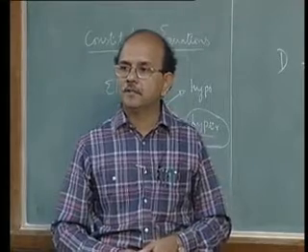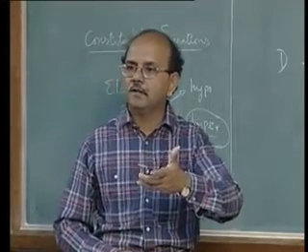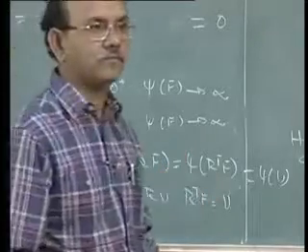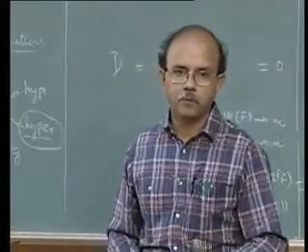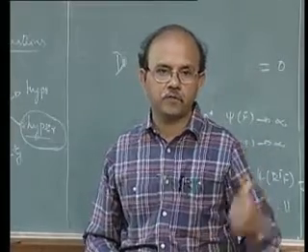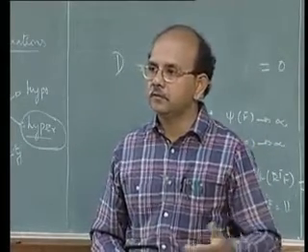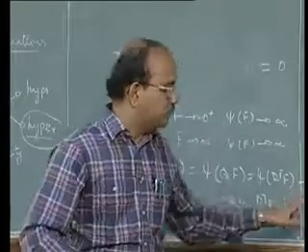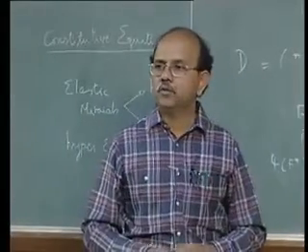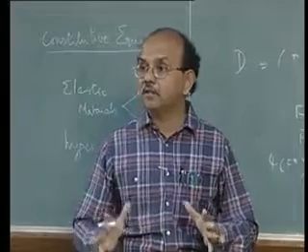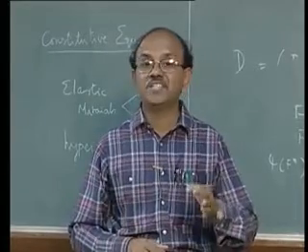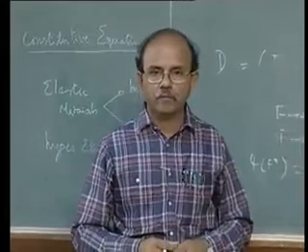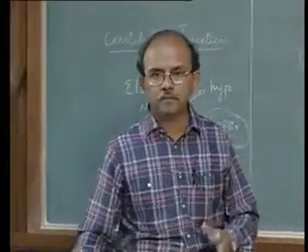Why? Because then I can just rotate a piece, and if this strain energy function respects it, then I would get a stress. After all, P, the Piola-Kirchhoff stress, is a function of the dou by dou F of this function. So fortunately it doesn't happen like that, and so ultimately this function reduces to a function of only the stretch alone. So in other words, a function of U. Is that clear?